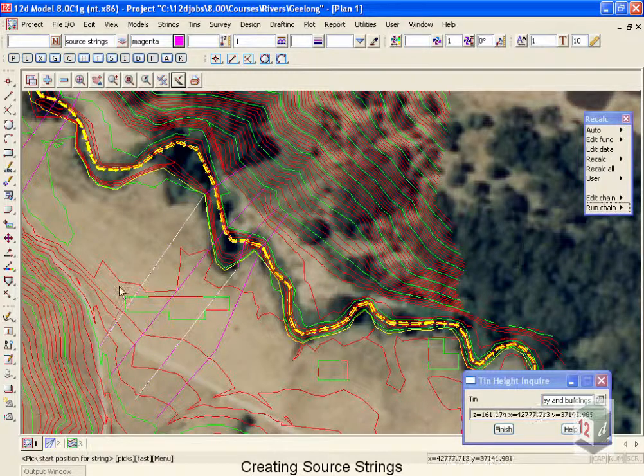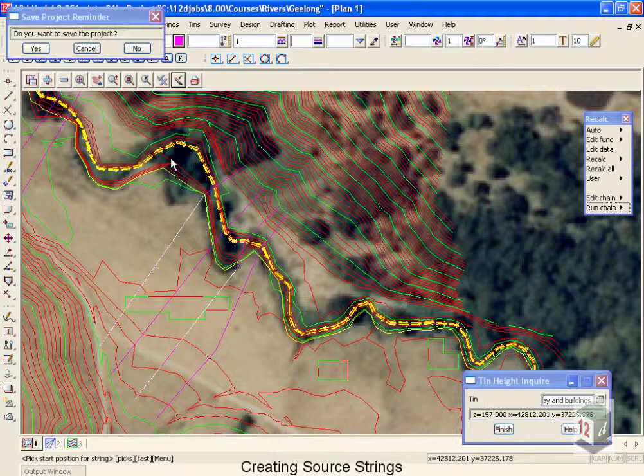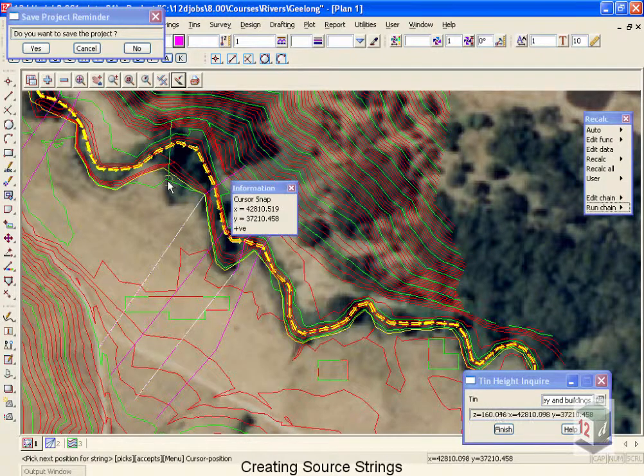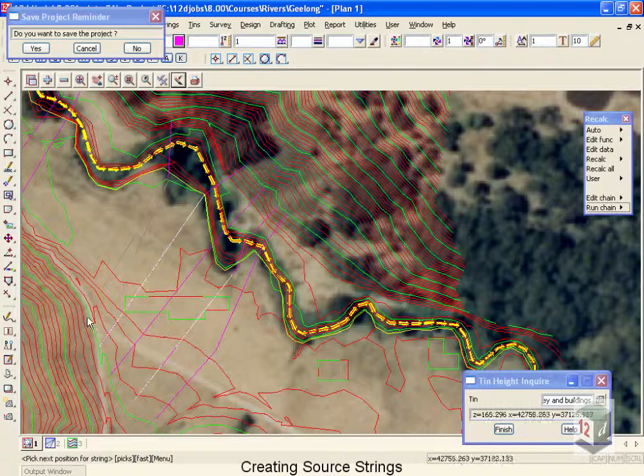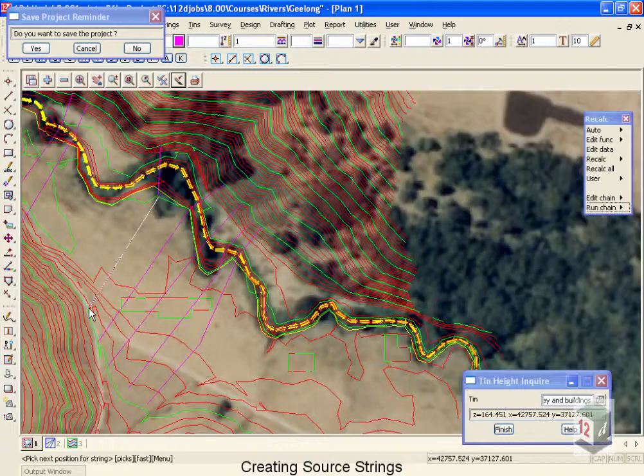And then of course we would want another one indicating where there's no more building at all. And we want to mark the end of the wider section of our river. So I'm going to come back up here to my 165. Bring this across perpendicular to my direction of flow. And once again, that compromise between the flow direction that you expect in the high flows compared to the low flow conditions.